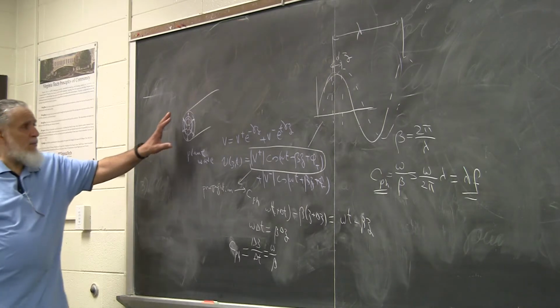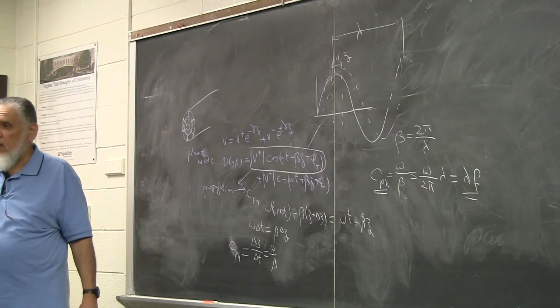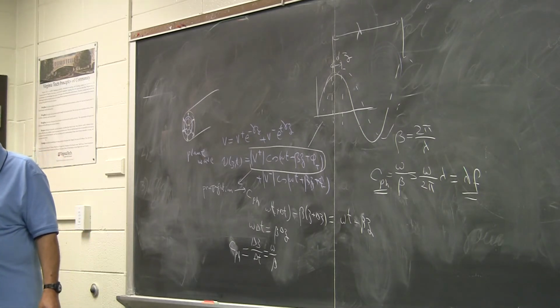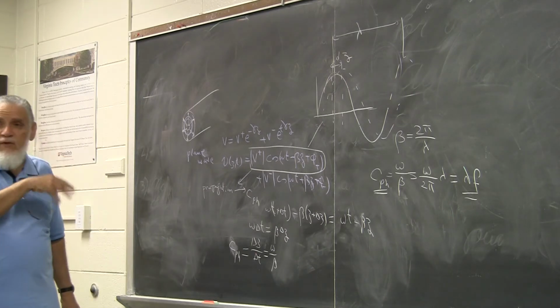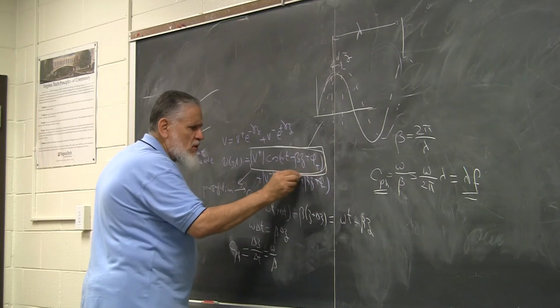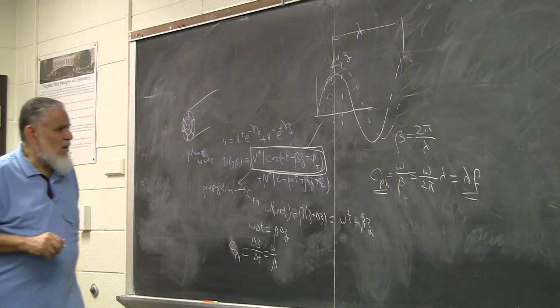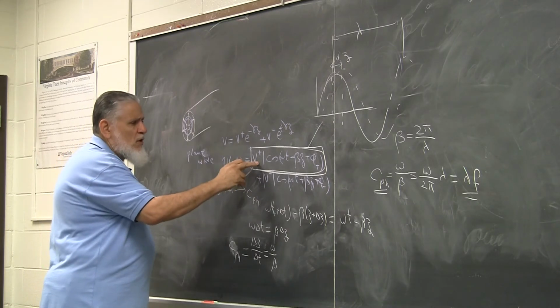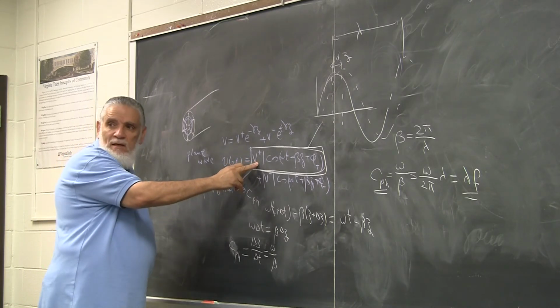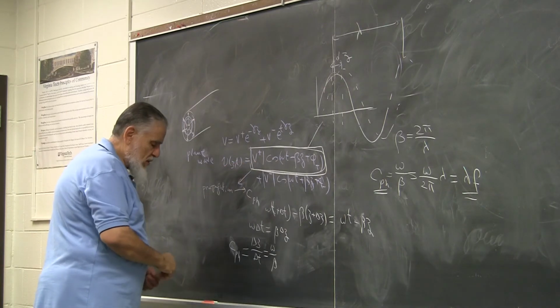Now, this can happen in waveguide, it can happen in a transmission line, it can happen in open space. If we have a plane wave, it's the same feature, because it's actually controlled mathematically by this equation. That's the equation of a plane wave propagation. There's no function here except for z. There's no x and y variations, right? There's no x and y variations.